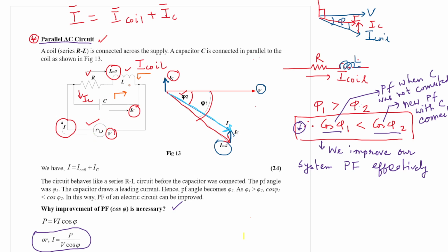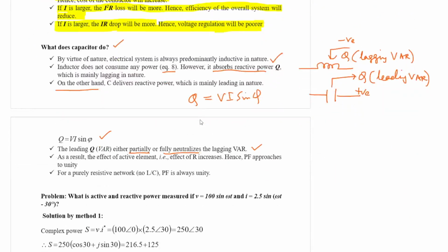Before the capacitor, it is drawing reactive power from the source. However, when the capacitor is connected, the capacitor is now delivering. So the burden on the supply reduces.